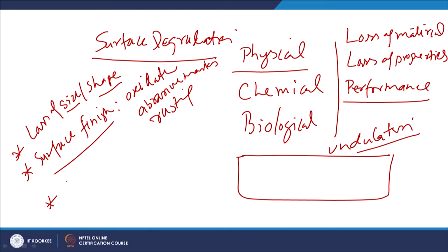In some cases, a combination of stresses as well as chemical interactions leads to cracking and fracture. Cracking and eventually fracture may appear through phenomena like stress corrosion cracking. It starts from the surface in the form of crevices and deep pits, and then, coupled with tensile stresses, it may lead to complete fracture due to the faster growth of the cracks.